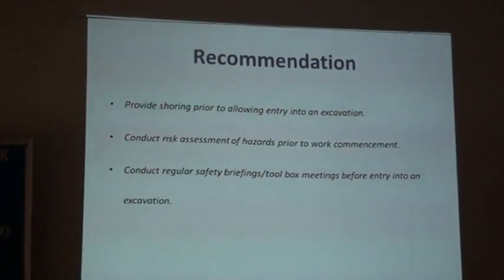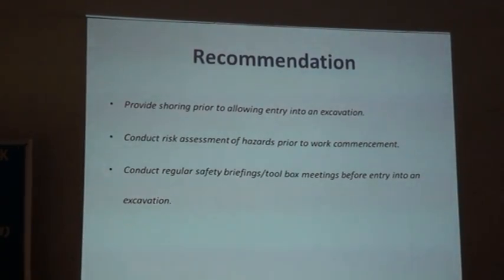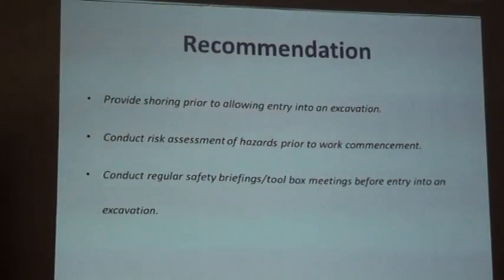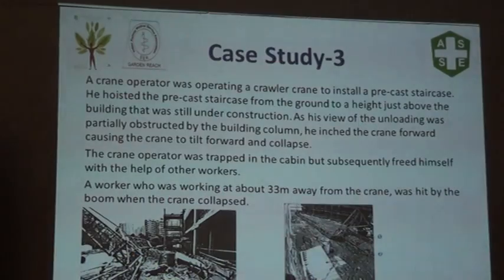So again, we have all these measures to be taken care of by conducting the required inspection, providing the shoring, and also going with the barricading, and removing the excavated soil from the edge of the excavated pit.